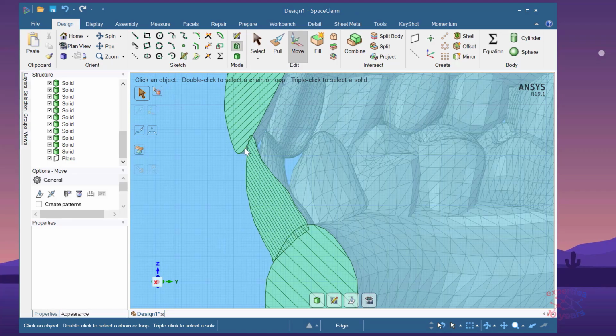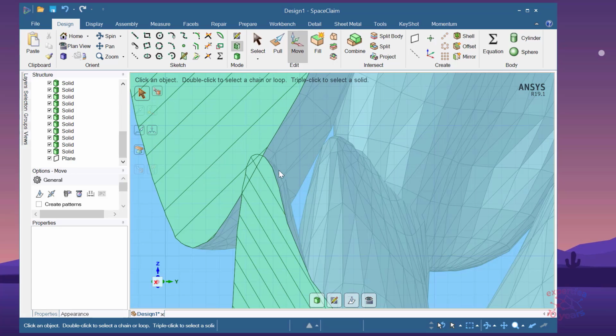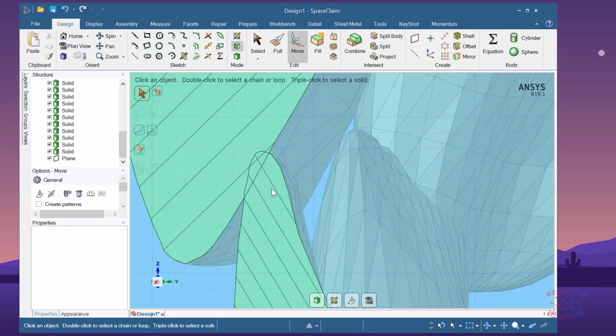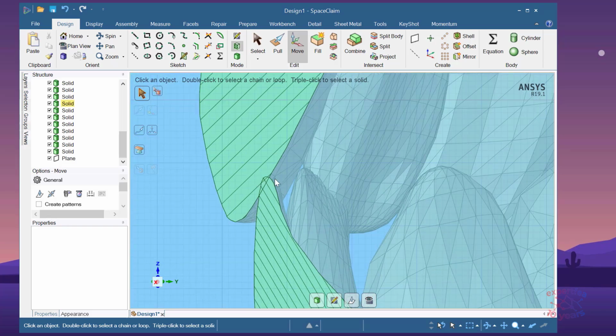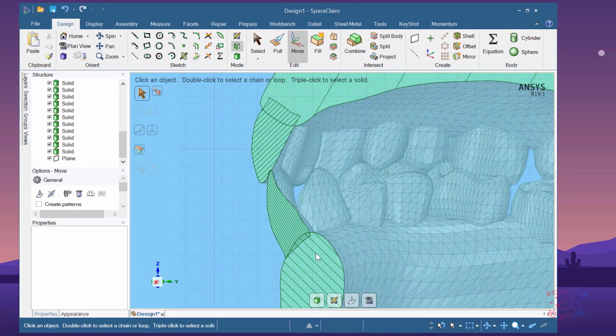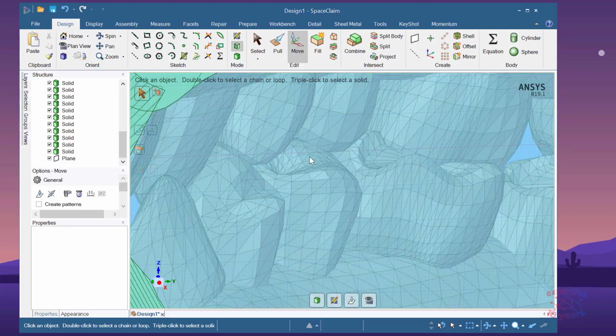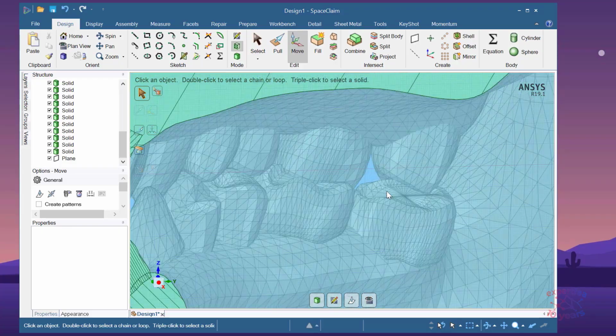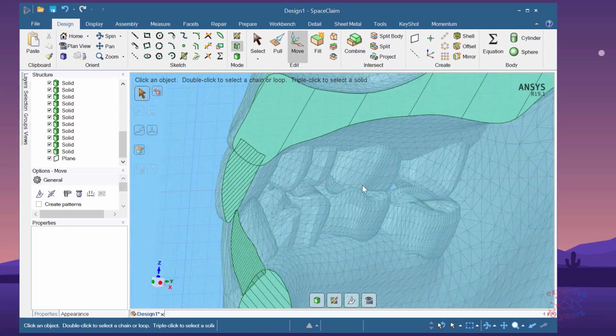Let's do our best to correct all of these, because a base, axiomatic principle states that two bodies should not occupy the same space at the same time. This is a golden rule. We should ensure this in our 3D models when and before performing simulations. We can take a look inside also, and see that the teeth do not touch correctly.